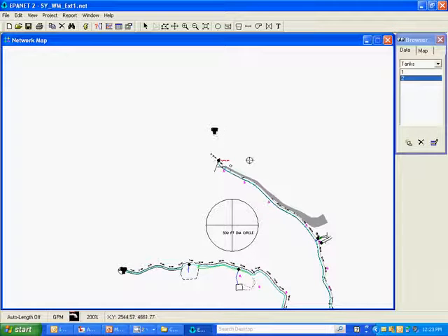If I drew this tank where it actually is located, it would be off the screen, and the area of our model would become so large it would be hard to scroll around in it. We're not that interested in this tank apart from its role in supplying a certain pressure of water or head of water there. So we'll just set the elevation of this tank at the actual tank elevation, draw a pipe and set the length of that pipe approximately to what the length is from the pipe to this point at the end of the system.